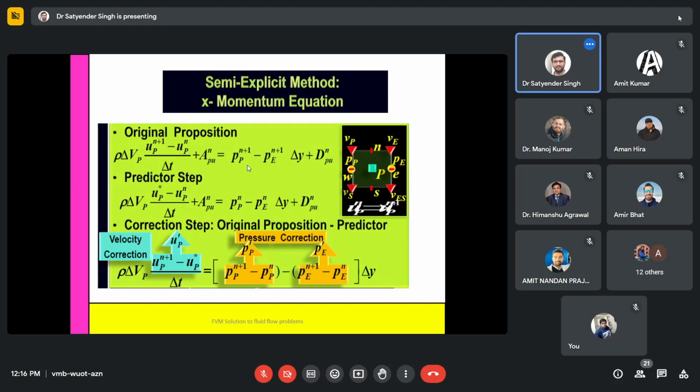And then for the other remaining walls, three walls for a 2D problem, we apply pressure gradient equal to 0 at these walls. One mathematical form, let's say del p by del x equal to 0, if you discretize it using, let's say, a finite difference method, represents the difference between two grid points at a particular extent, delta x or delta y, equal to 0.